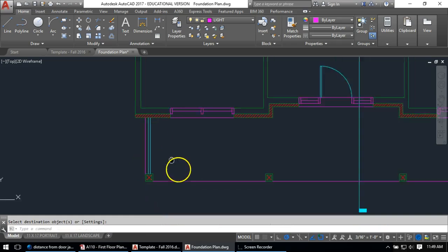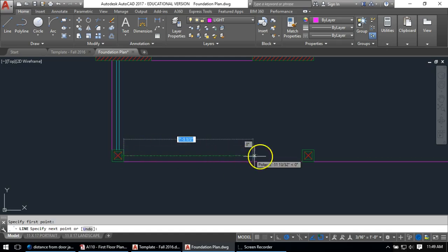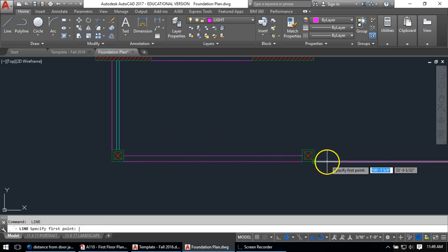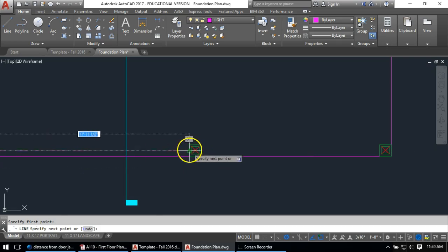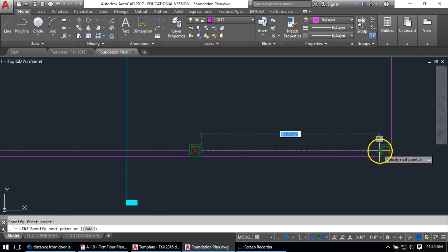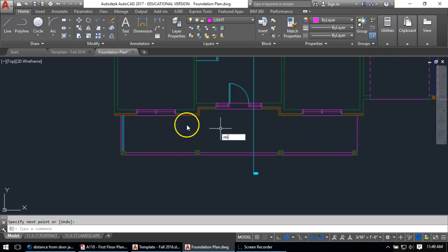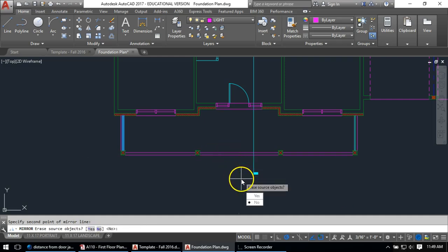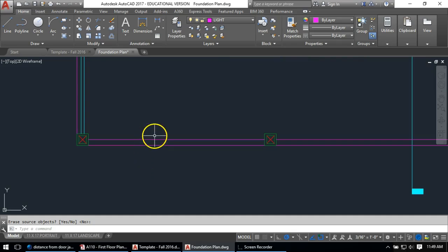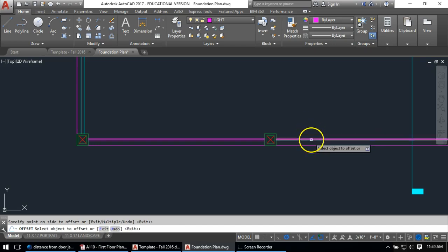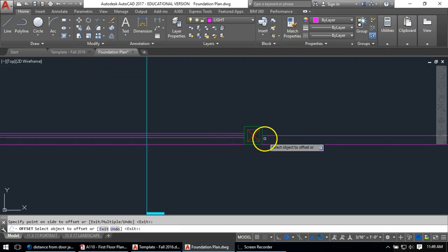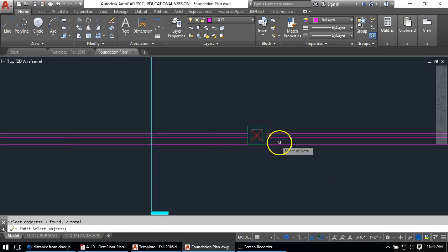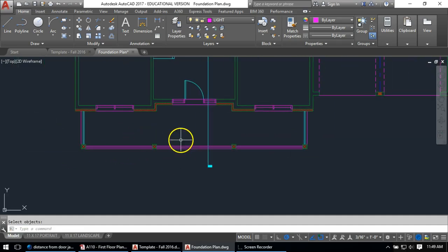So there's going to be a few different line weights in there, and of course it's going to come centered across here as well. There to there, I can just draw the center line. Again, I know I have to come and clean this up for the stairs, but I'll start that way, go here, and this railing is going to be the same, so I can mirror this from my midpoint right over to keep that. But these I have to build offset 1 inch on each side. Erase the midpoint line and change the layer.